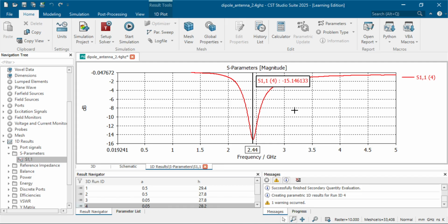Since these are narrow field antennas, we try to decrease the radius, and for a greater return loss, we keep in account these two parameters as well. So for a standard dipole antenna, 15 decibel return loss is pretty good, and a bandwidth of 10 to 15% is optimal, but less than that is excellent.